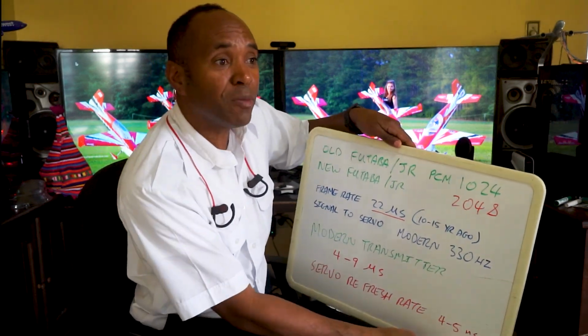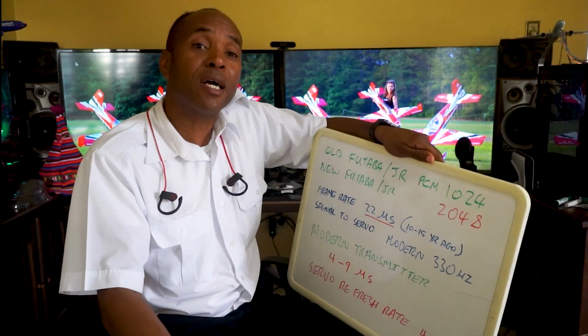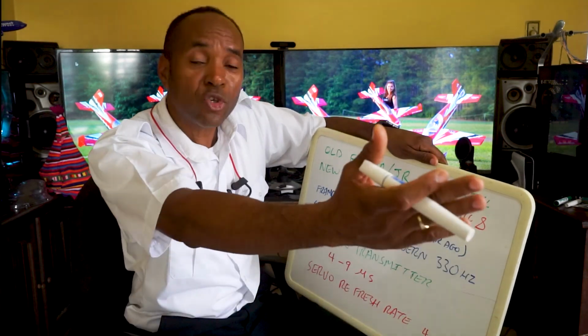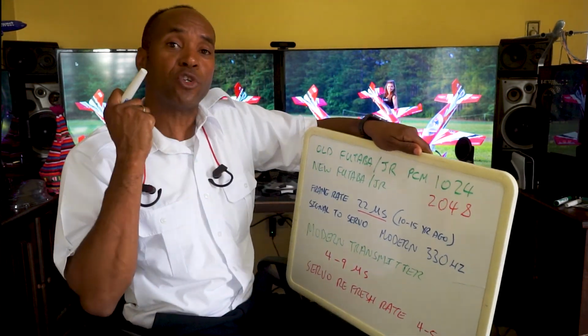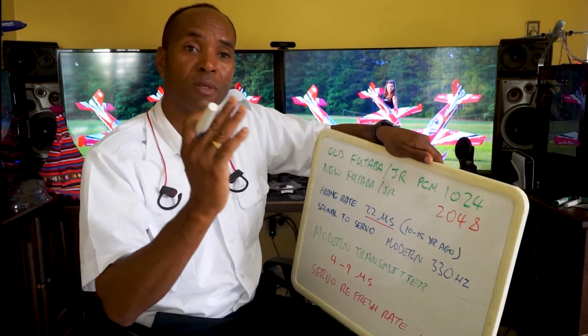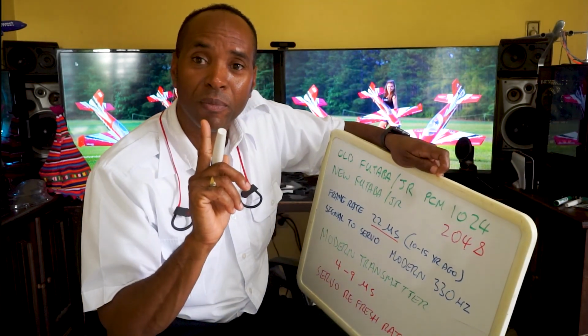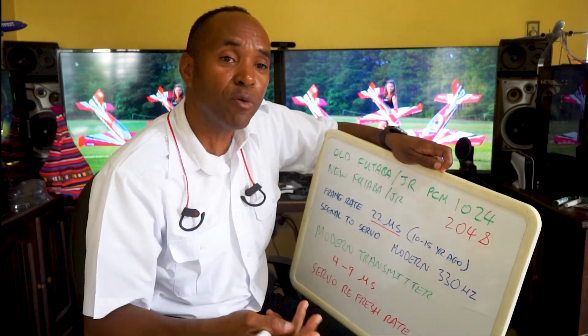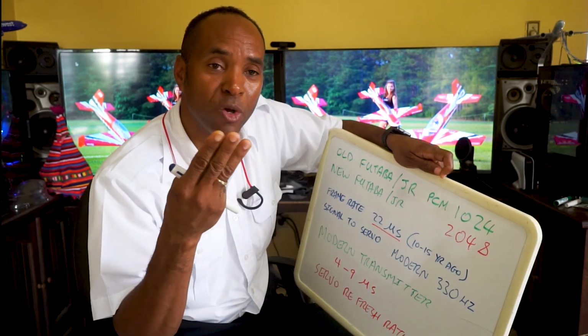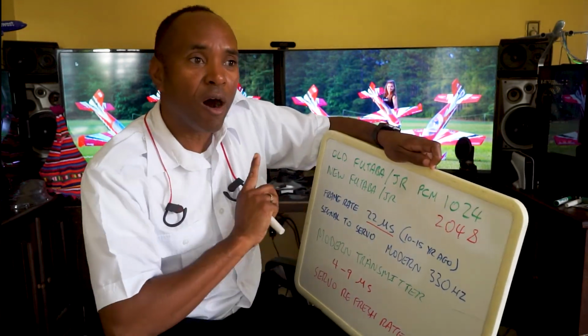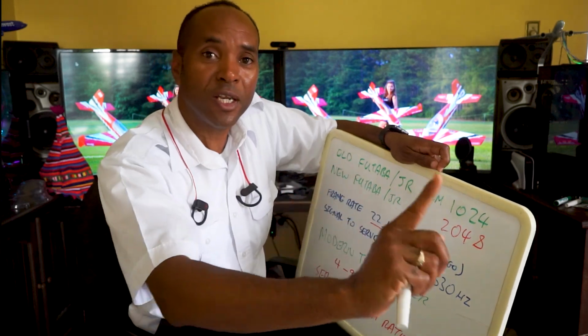An S-bus system, let us think about robotics. Let us think about a robotic arm with 16 servos to perform the same function in unison. All of them will get the same signal through the same wire, right? That wire would be the middle wire in your 3-wire RC connector. All the servos are following the same signal in unison.